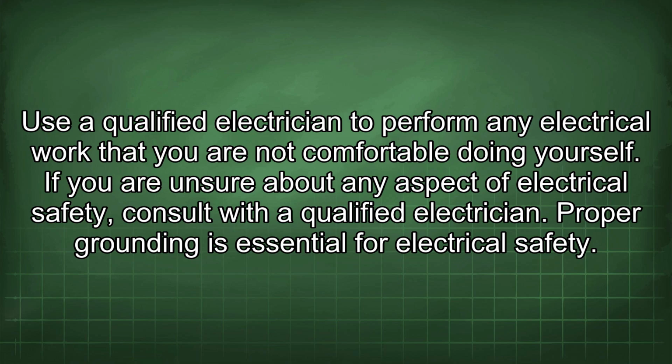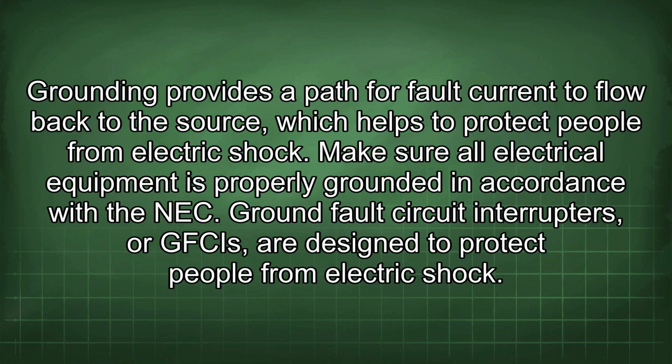Proper grounding is essential for electrical safety. Grounding provides a path for fault current to flow back to the source, which helps to protect people from electric shock. Make sure all electrical equipment is properly grounded in accordance with the NEC.